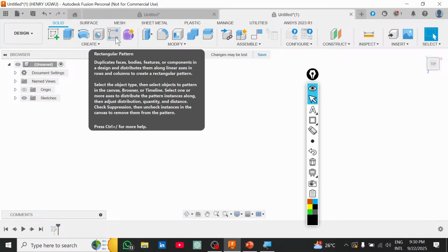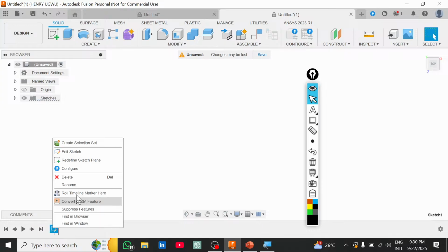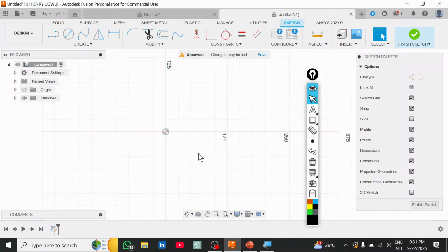But we are not done with that, so you want to go back to your sketch. Remember what I told you about the history tab here. See our sketch: because we created the sketch, it has been recorded here. So I don't need to undo or create a new one. I can just go back to that, right click on it, and scroll to edit sketch. Let's click on edit sketch. So we are back in the sketch environment.